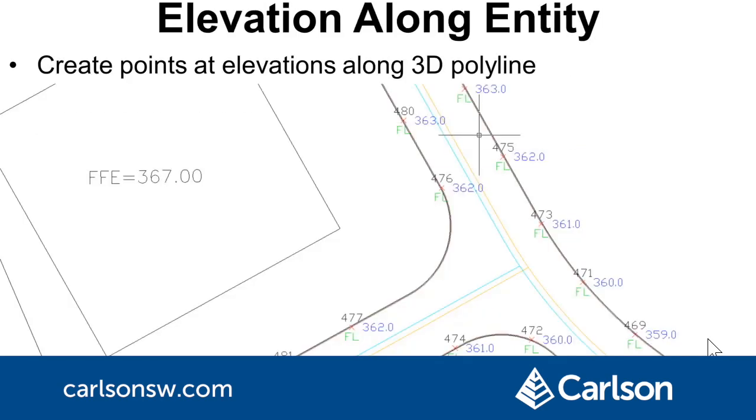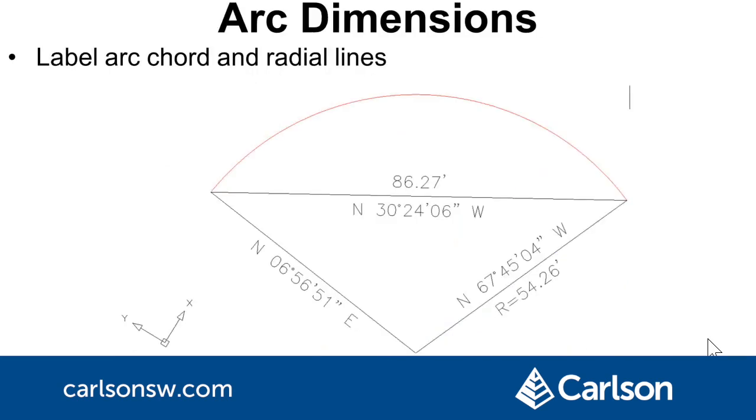Elevation along entity is a new command to create points at elevations along 3D polylines. You can enter an elevation interval or specific elevations. Arc dimensions is a new command to label the chord and radial lines for an arc.